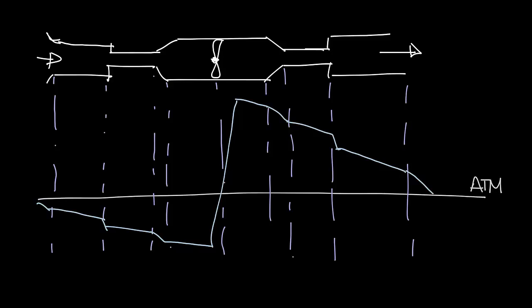So now let's go back and do the static pressure as well. So the static pressure goes down with the total pressure. We have a transition here. We lose total pressure, we lose static pressure. A little more straight duct. Now here you get an expansion, so the velocity slows down, the static pressure will go up along the ductwork, gets a boost through the fan, following along the ductwork again here.